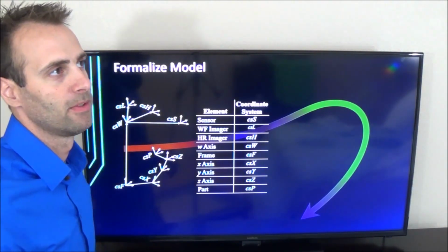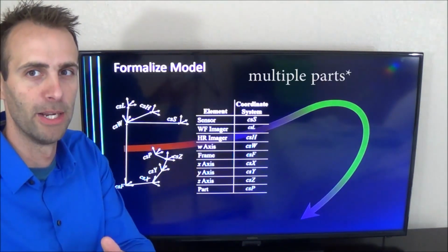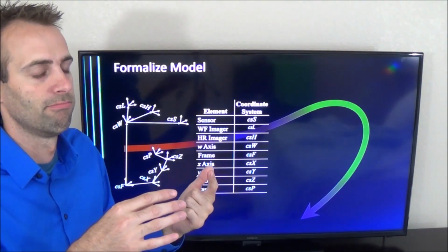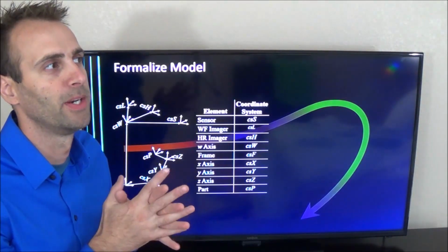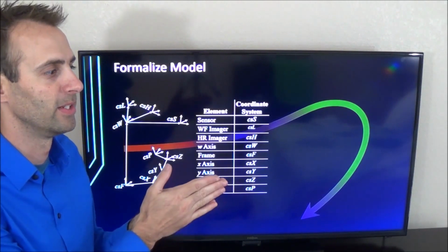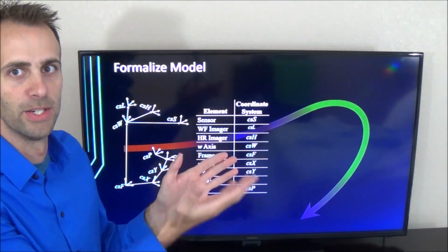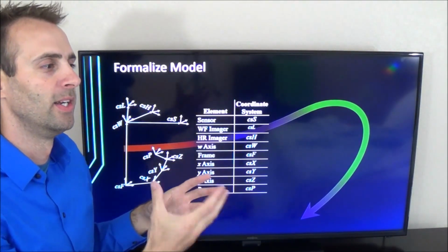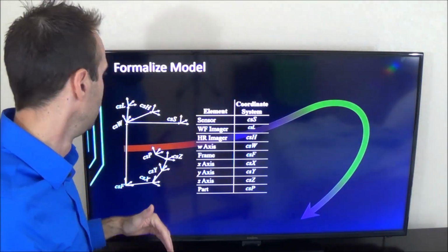And then you have this order. Well, how do I cope with multiple tools on my table? Because that's not really a continuous chain anymore. Now it's more like a tree. And if I want to compare that, when I do a G54 offset on a milling machine, what I'm doing is I'm telling my machine that the part coordinate system all of a sudden changed, so that way I can repeat that same code without having to add all of that to that file.